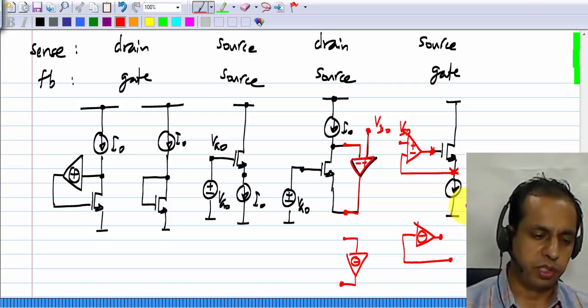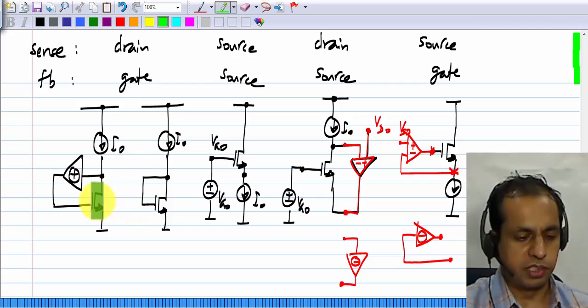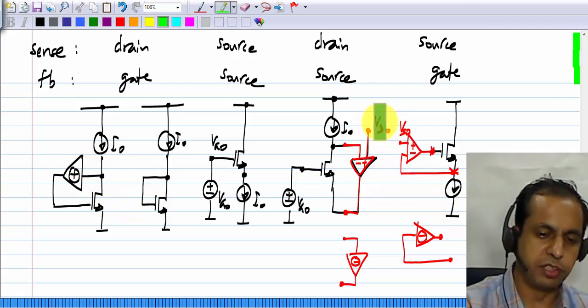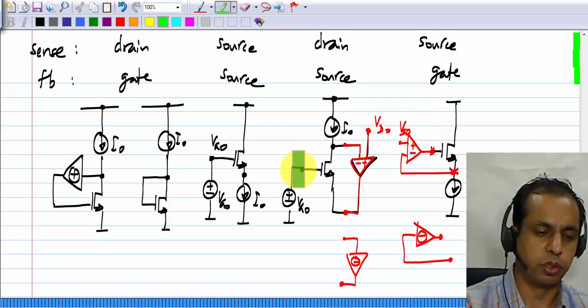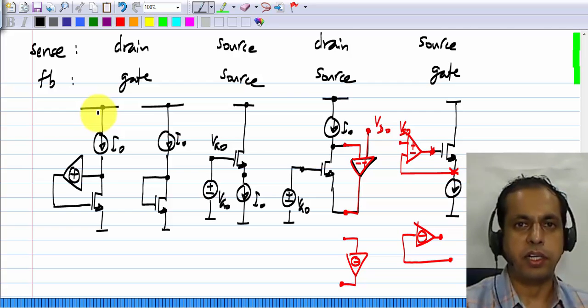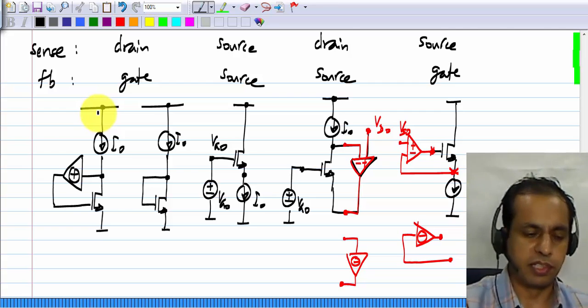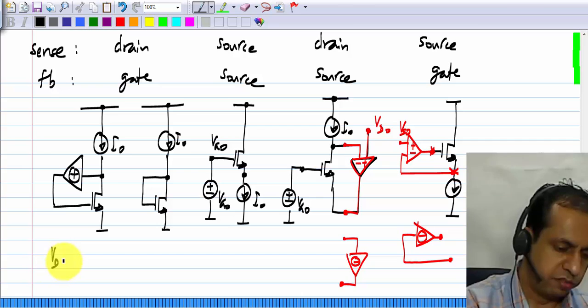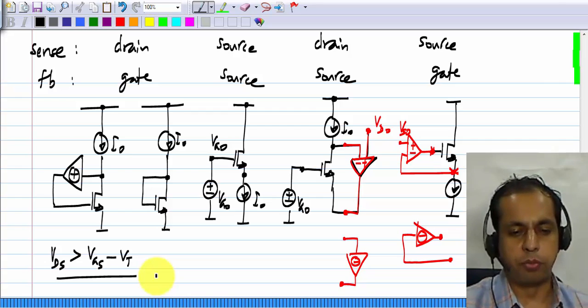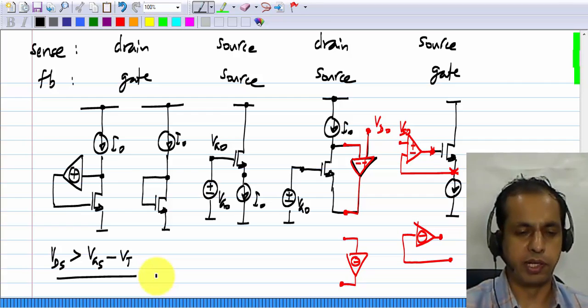Now, after you do this, there are of course many realizations possible for this positive incremental gain or these negative incremental gains, and choice of these bias voltages Vd0, Vs0 and so on. After that, you have to check separately and ensure that the transistor is in saturation. So that means that Vds is more than Vgs minus Vt. I'll show it for a couple of examples, and you can work it out yourselves from assignment problems or activity problems, and you can even create your own examples.